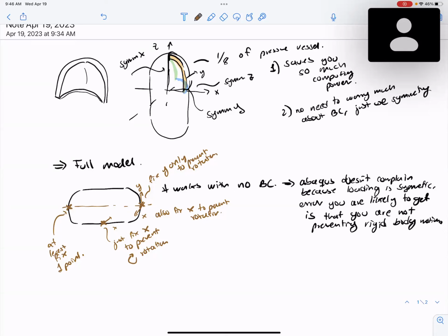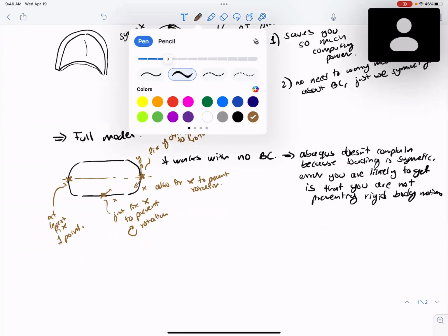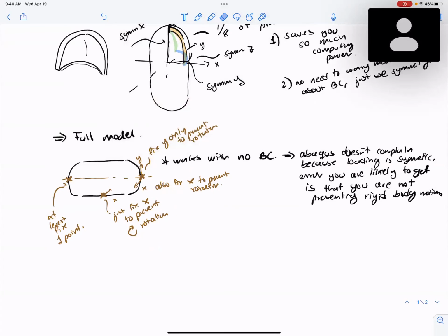So you have to measure. You can get a hex mesh, but if you got a TET mesh, that is okay, as long as you do the mesh convergence. So as long as you generate multiple meshes and make sure that your stress basically reaches a certain value. I haven't looked at the reports, but even if it was a TET mesh, that is okay.